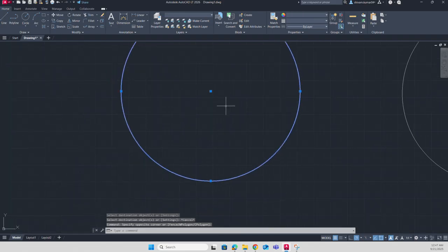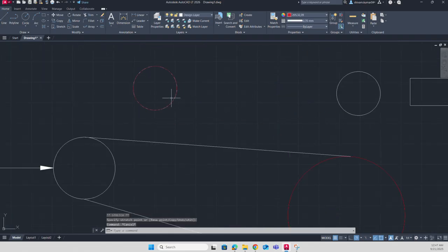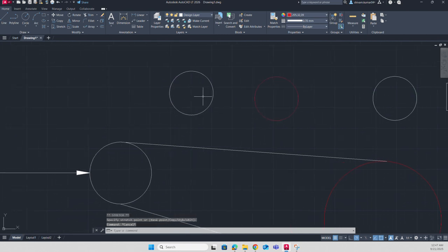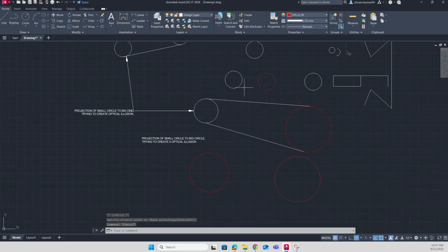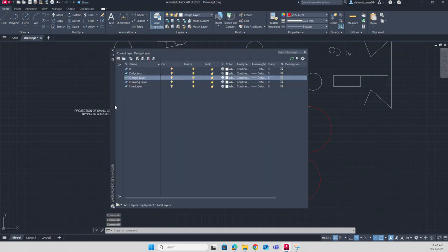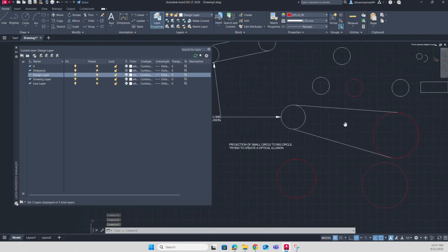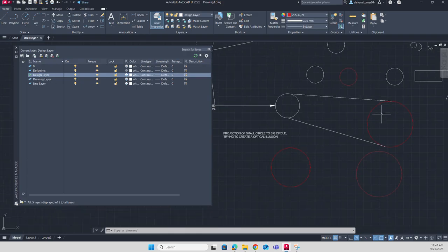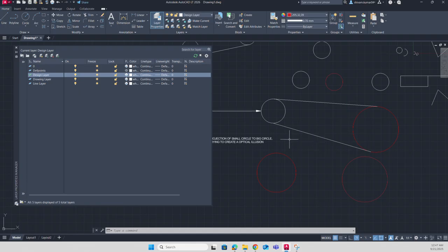You can see your object. There are two objects, I think, over here. Let me move one. Okay. Let me select. Yeah, there are two objects over here. You can see the top one I have selected. So these are the layers. Now in the layer section there are multiple things you can do, like lock, unlock, freeze, unfreeze on the layer. Let me open the layer properties, and let me drag in this direction, and you can see at this stage the design layer. So whatever object you can see on this model space, everything appears.